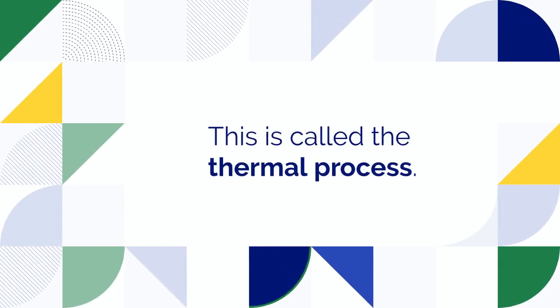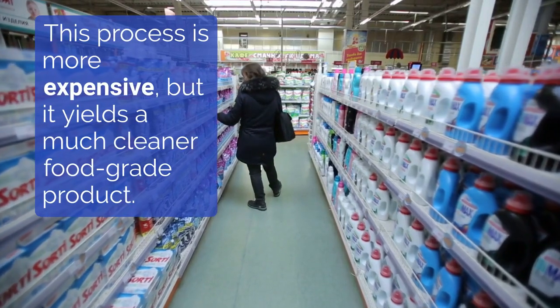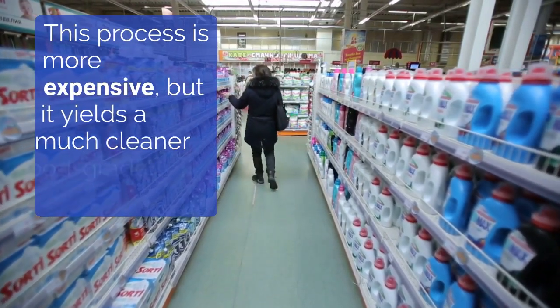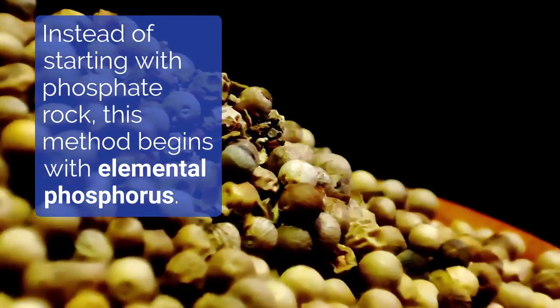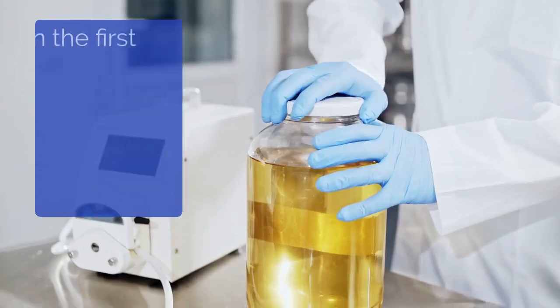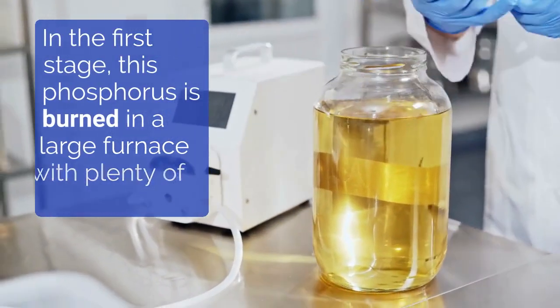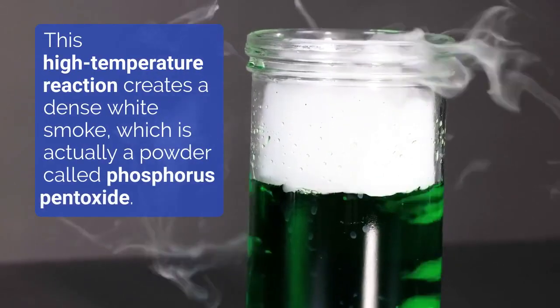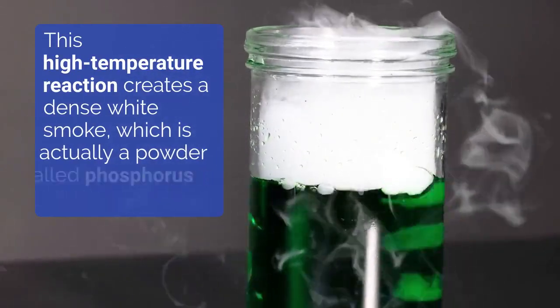Now, for applications where purity is key, like in the food and beverage industry, a different method is used. This is called the thermal process. This process is more expensive, but it yields a much cleaner, food-grade product. Instead of starting with phosphate rock, this method begins with elemental phosphorus. In the first stage, this phosphorus is burned in a large furnace with plenty of air. This high-temperature reaction creates a dense white smoke, which is actually a powder called phosphorus pentoxide.